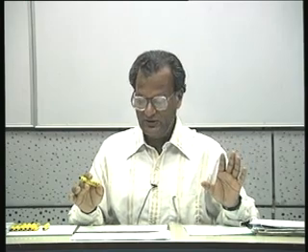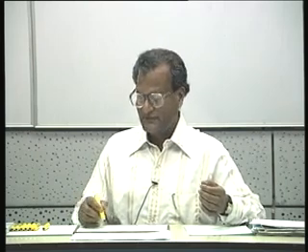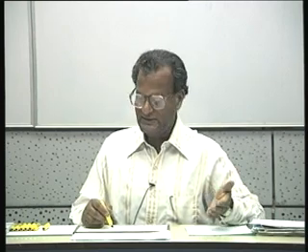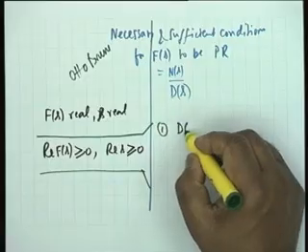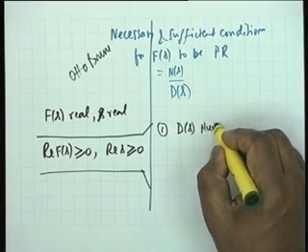Not zeros. He says, take the function and test whether all poles are in the left half plane or not. Closed left half plane. How do you test that? You perform Hurwitz test on D of s, on the denominator. Poles are the zeros of D of s. So, first question you ask is, is D of s Hurwitz?